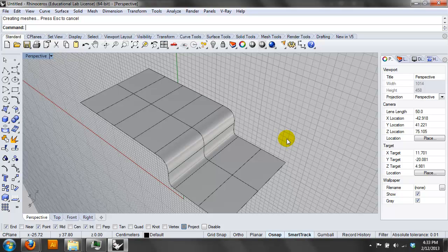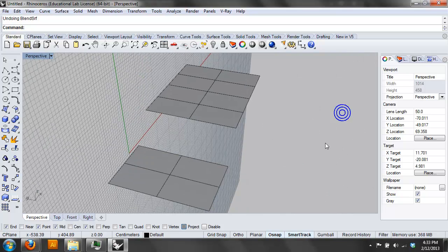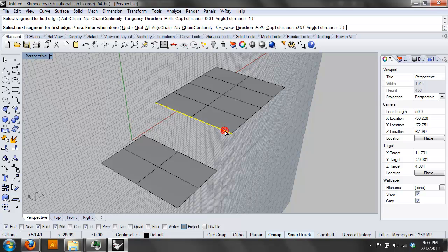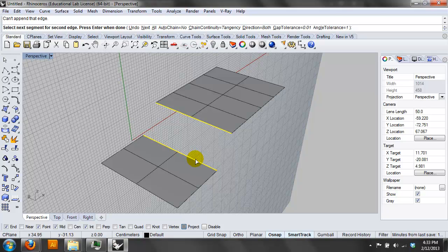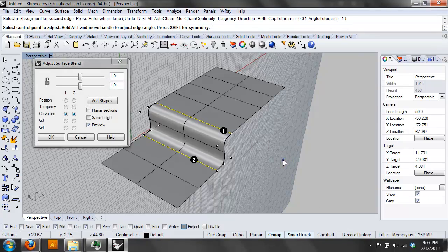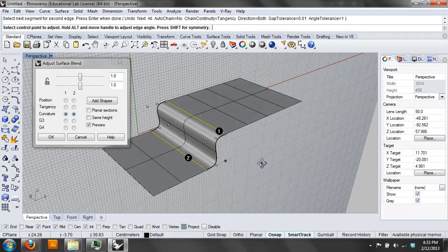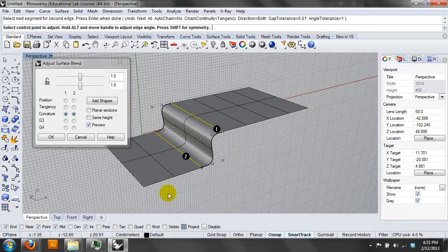But a blend again gives you control over both of those curvatures. If you're having trouble with that surface, sometimes things have a direction to them, the direction that the curve is drawn or the surface gets drawn, and so sometimes you have to flip the object, or play with the direction of it. In this case, it looked like I had to do this one first and then that one because of the way that the polygons get drawn.